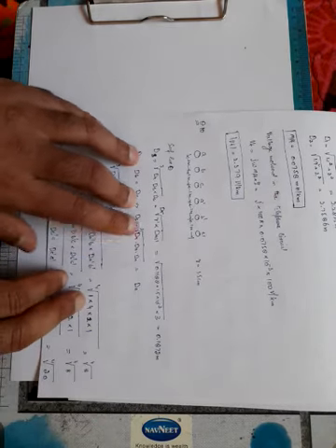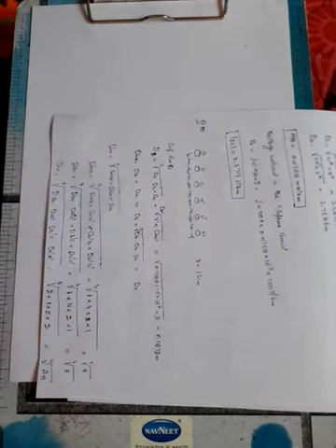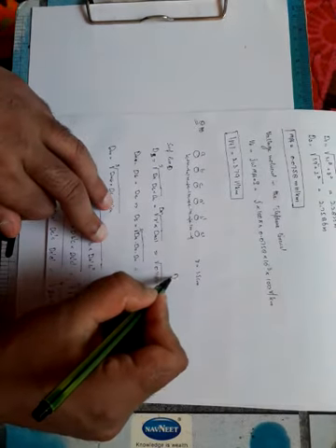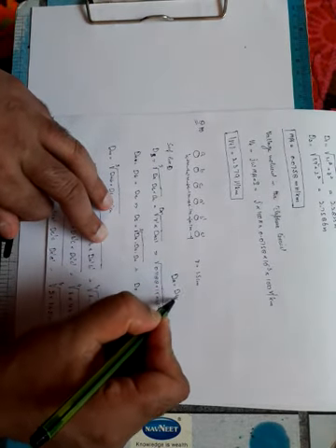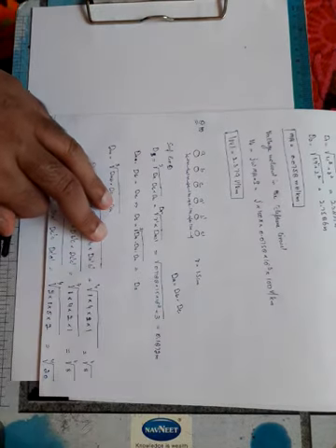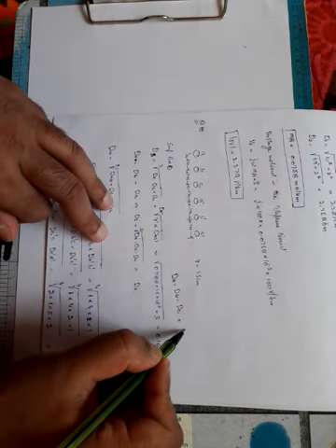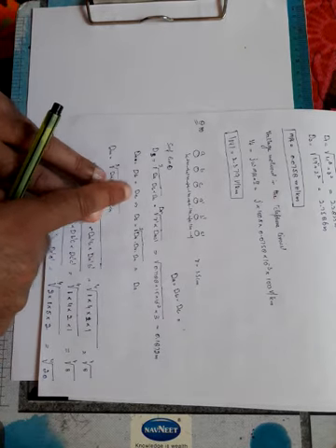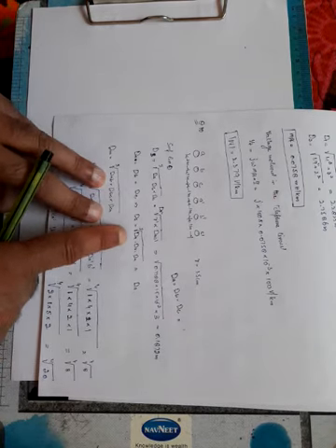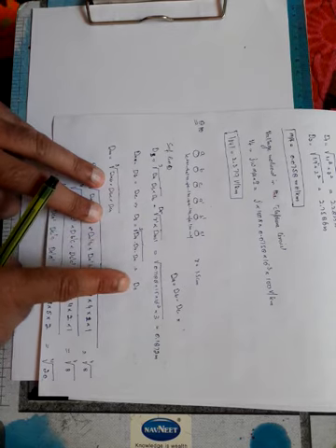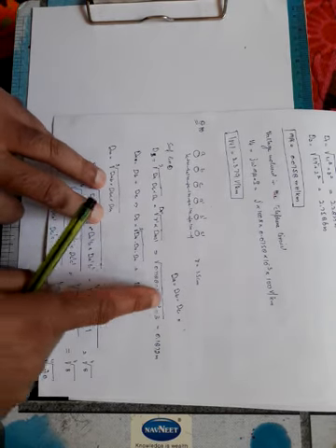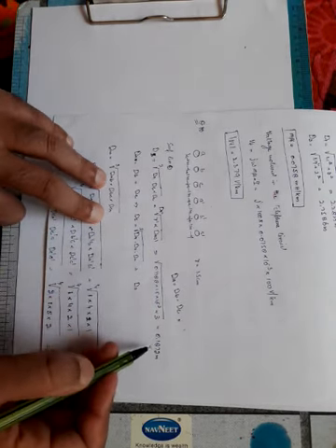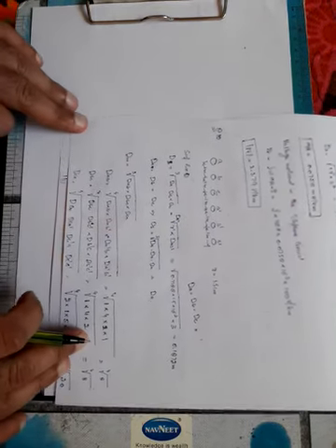That means dA will be equal to dB will be equal to dC. So Ds will be equal to the cube root of dA into dA into dA, that is simply equal to dA. So I calculate only dA, that is equal to 0.1872 meter.